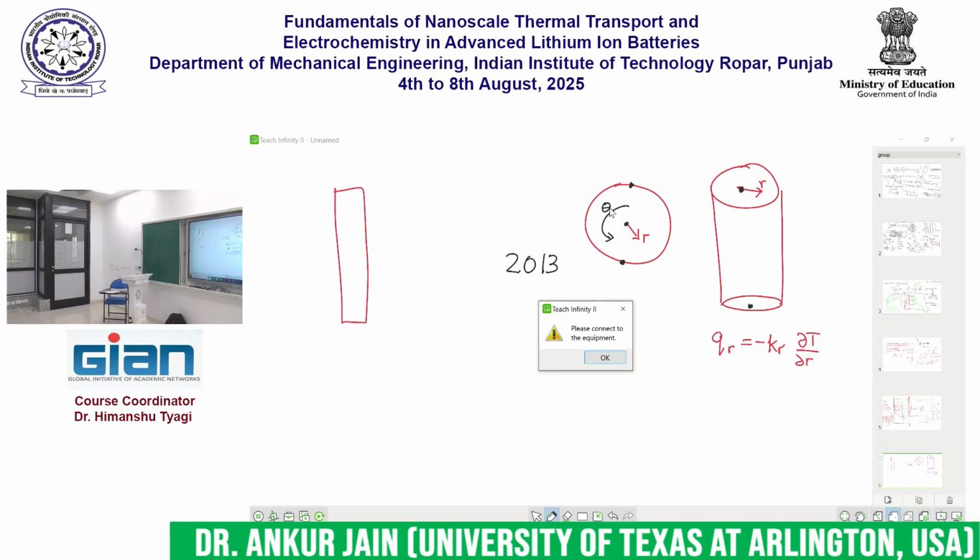For example, in this case, in order to force two-dimensional flow of heat in the r and theta direction, I need to place a heater only along a certain circumference, right? I don't want to put it all around.